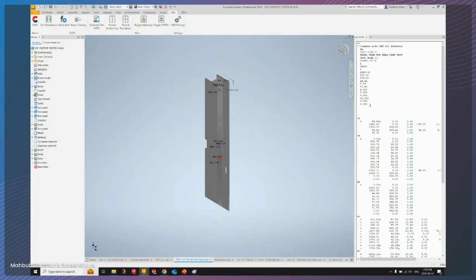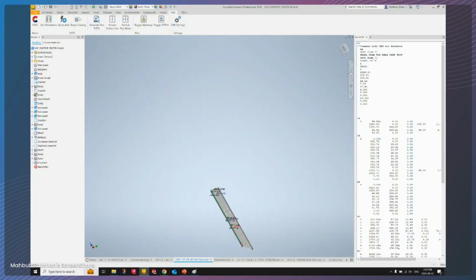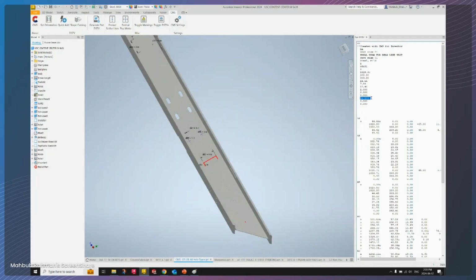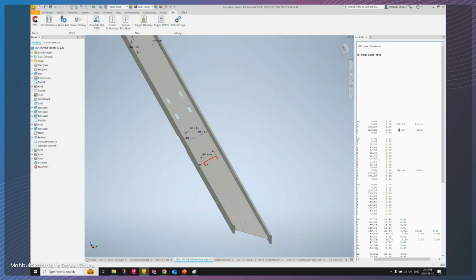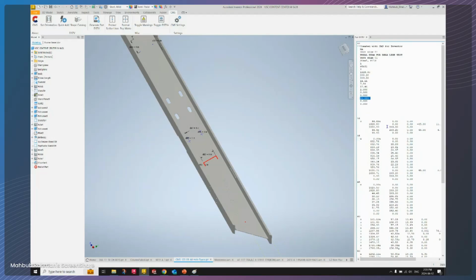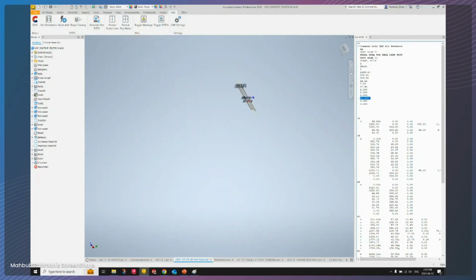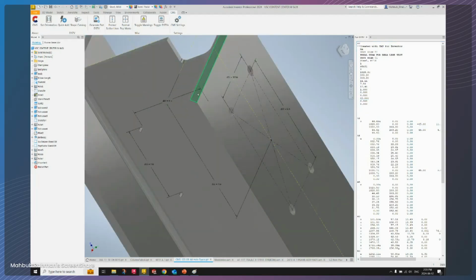One of the things that I mentioned is that our software will also be grabbing your miter angle. As you know, we have a 45-degree miter over here, right? And this miter is the 45-degree angle. As I said, some of the machines cannot read those angles from here. In order to add bevels, you still need the bevel details. So those bevel details are part of the AK that's been added here as well. Additionally, the software also added on the top flange, we had 2 bevels. The reason why we had 2 bevels on this side, and the other one was from there, right?